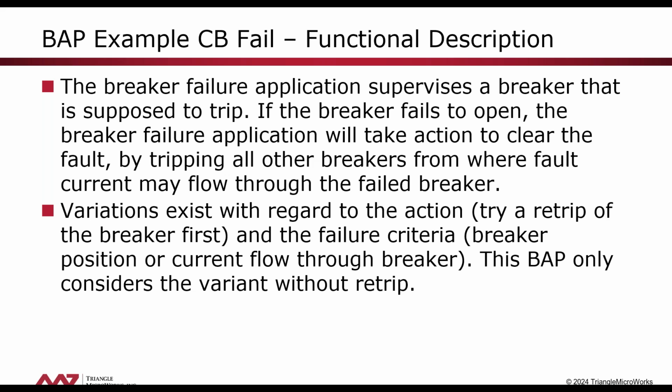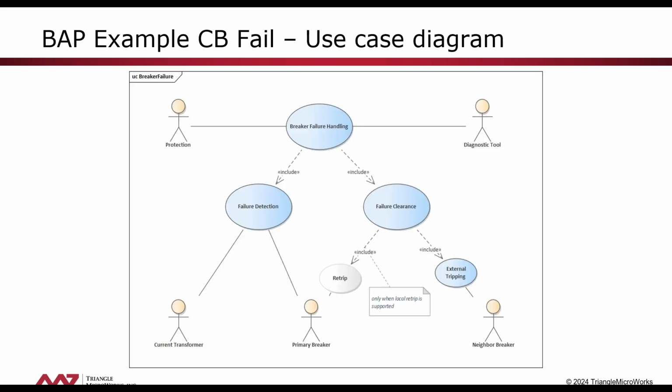And then it gets a little bit more formal. It has then a use case. So we describe the application as a use case with a use case diagram. We have the protection as an actor that initiates the breaker failure function. So the breaker failure handling includes the use case failure detection. It supervises the current and the position of the breaker, that the position opens and the current goes away.